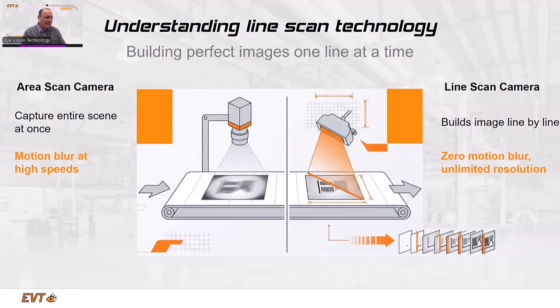So if you use an area scan camera, the image capture speed or the shutter speed or the maximal capture speed is not so fast as for line scan cameras, which finally results in a problem of unsharpness in the moving direction. And therefore, at least based on this, line scan cameras are much better.